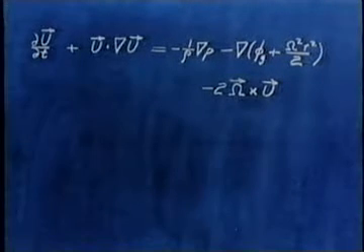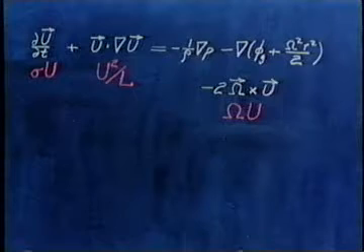Two dimensionless parameters characterize the relative importance of fluid accelerations as against Coriolis forces. They are the Rossby number and the frequency ratio. These parameters arise naturally when one estimates orders of magnitude of the terms in the equation of relative motion. The required terms are of these orders.